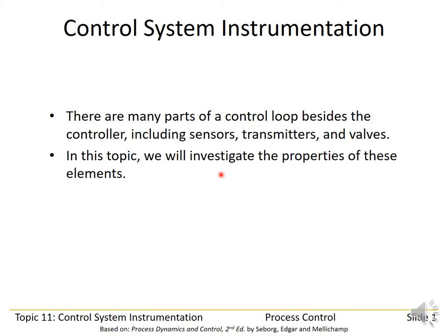In particular, we had an instrument that made a measurement of the composition. We had a transmitter that transmitted that signal to the controller. And then after the controller, we had a control valve.